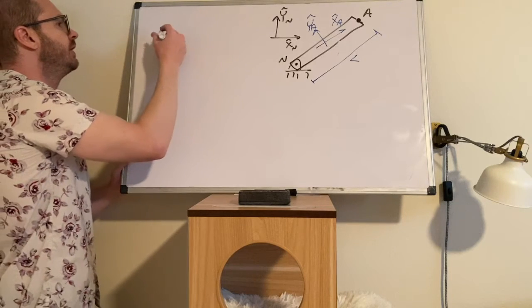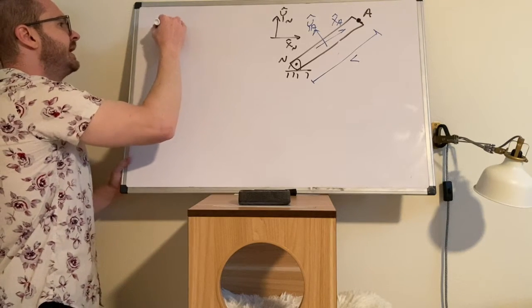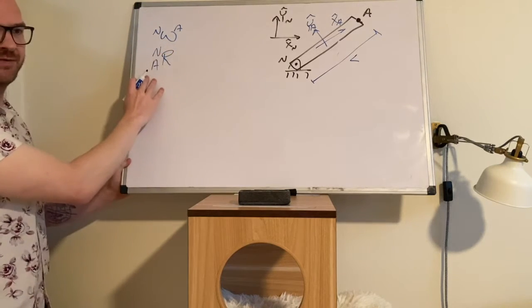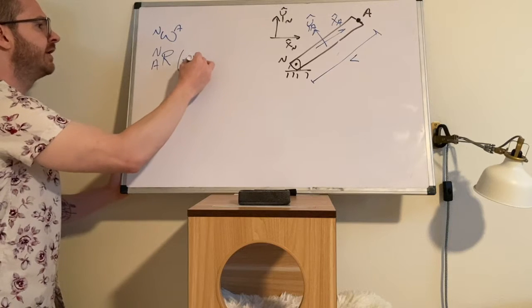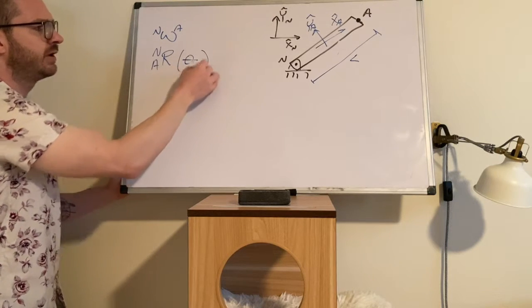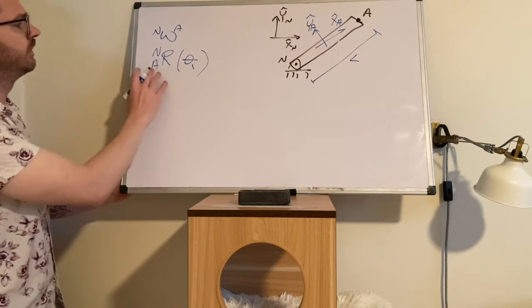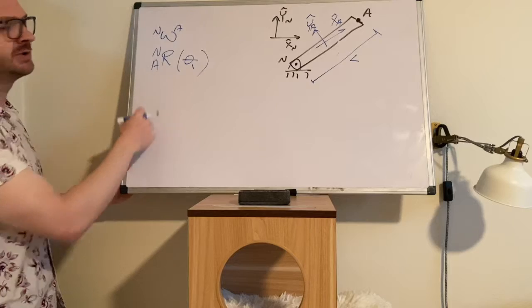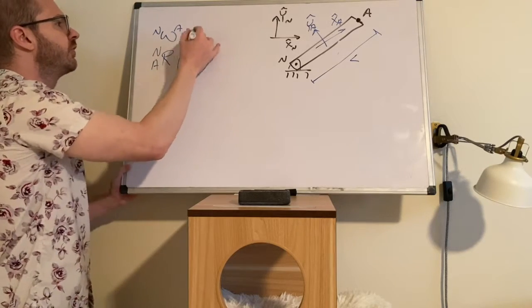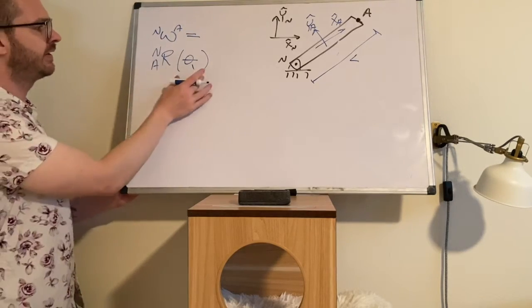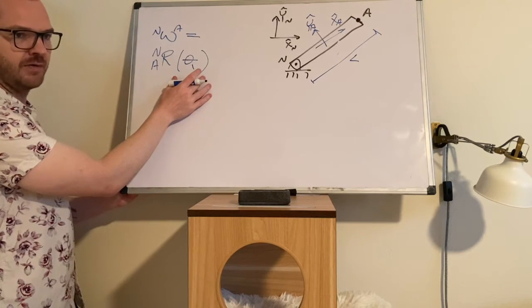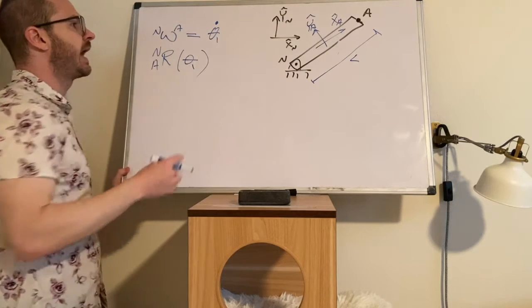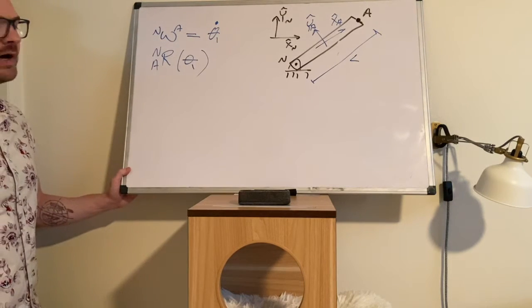So what are we going to do about omega n to a? Remember, we had defined the rotation r into a, and this was a function of the angle theta. We can call it theta 1, that's fine. So the theta in this problem, theta 1, is how we define this rotation. What we're going to do with omega is just take the rate of change of this rotation, which is going to be theta dot. How does the angle theta change with time?